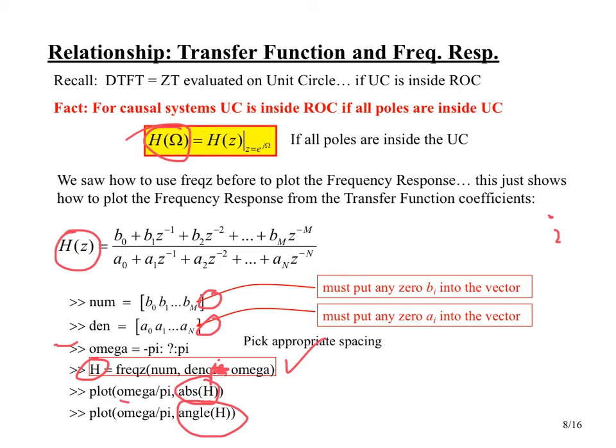And this is a little trick I do all the time. I plot it versus omega divided by pi. What that does is MATLAB will put a nice little grid mark at 1 when you plot, and you interpret 1 as pi, and -1 will be negative pi. And chances are it'll put nice tick marks at like 0.25 and 0.5 and things like that.